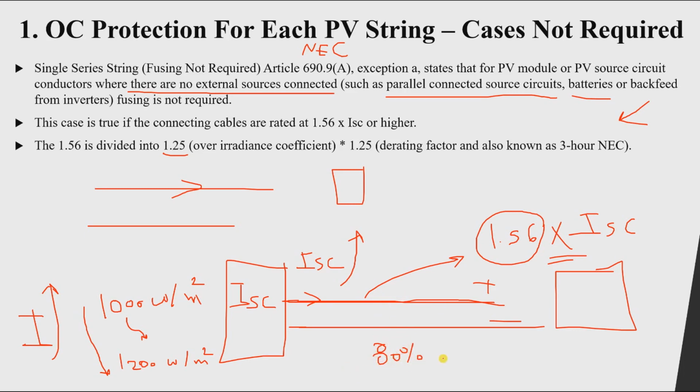So, for example, if we select a cable of 100 amperes and we know that current will go through it more than 3 hours continuously, we can only load our cable by just 80 amperes. Loaded by 80% only. Why? Because when this current goes through the cable, it will cause heat energy and increase the temperature of the cable. That's why we need to underload, or decrease the loading on, this cable. So if you have 100 amperes, you have to go down to 80 amperes only.